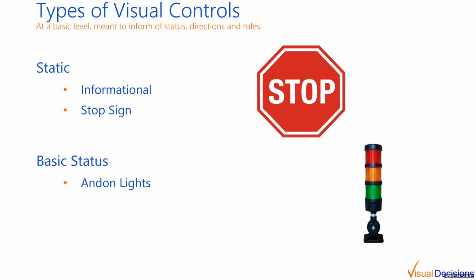One note I will add though is items like an andon light showing the status of a machine right there at the machine can be enhanced through a simple app sending alerts to responsible people when the machine stops, giving the status of that machine in different applications and so forth. So that notification can also be directed to different people such as engineering, maintenance, supervisors, quality, etc., based on the primary fault code coming from the machine controller after the stop is detected. So while the basic andon light function wouldn't change, what you're doing with that information certainly could.